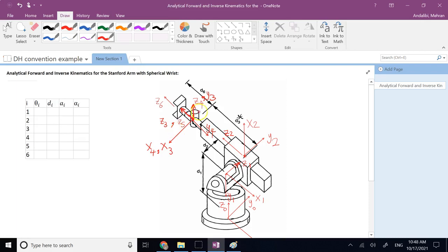And now again, if you look, Z4 and Z5 are perpendicular like that, and that makes my X5 the same direction. I can choose it to be the same direction as X4. And that makes 2 of my future thetas 0, plus, of course, the angle that I have, theta 4 or theta 5. But it reduces 2 of the offsets here.